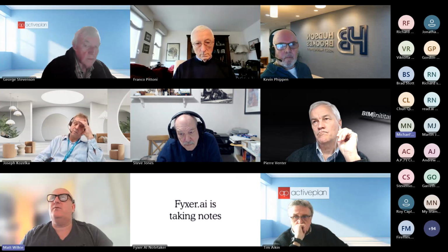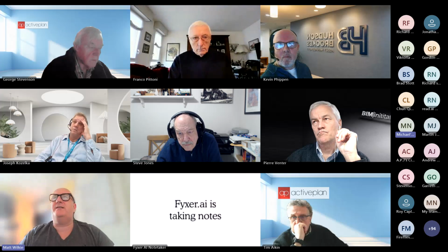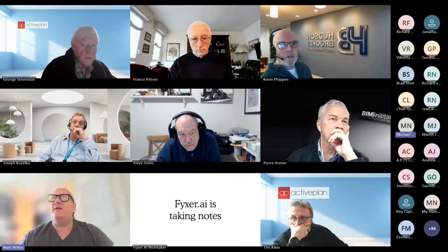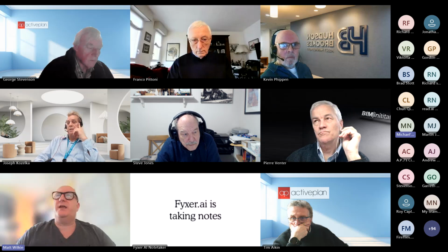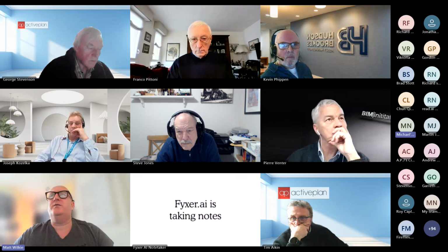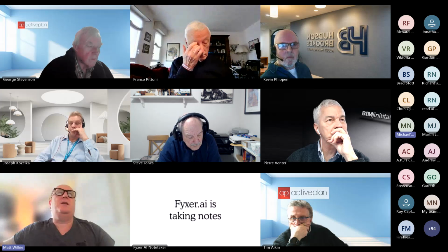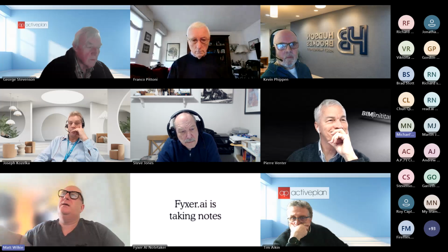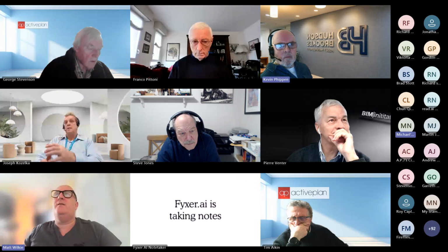Yeah, 100%. I'd also say this is partly why it's important that people update the RDSs. And when they do the ventilation changes, I think it falls under Part F of the Building Regulations, the British standards, isn't it? I'm sure it's Part F. So you're supposed to take air changes when you do those changes as well. So you're 100% right. If a wall's moved, the ventilation may be in a completely wrong place as well now. I've been in schools where all the supplies and extracts are together, and I look at it and think, well, I know what's happened there.